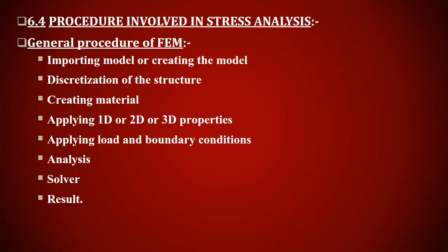After meshing, we create the material, then apply 1D, 2D and 3D properties, then apply load and boundary conditions. After that come the analysis, the solver and the results. These are all the steps under NASTRAN PATRAN software that we have to follow for completion of our project.